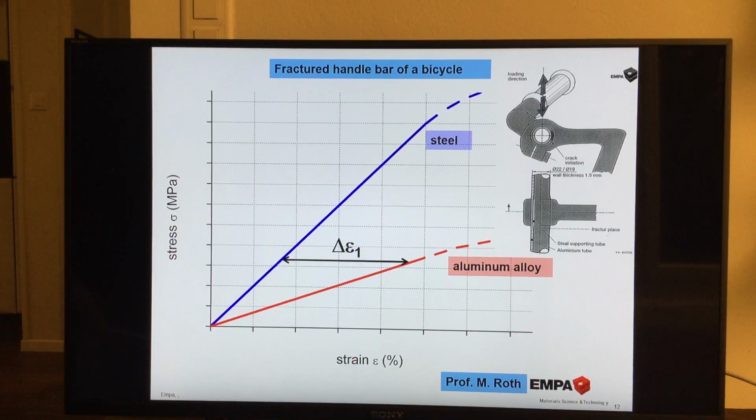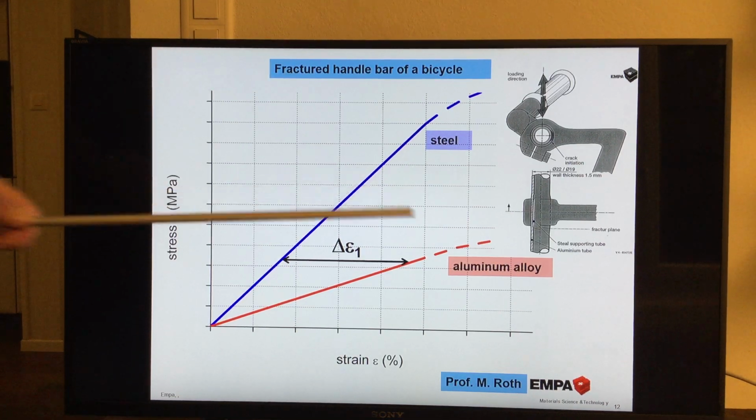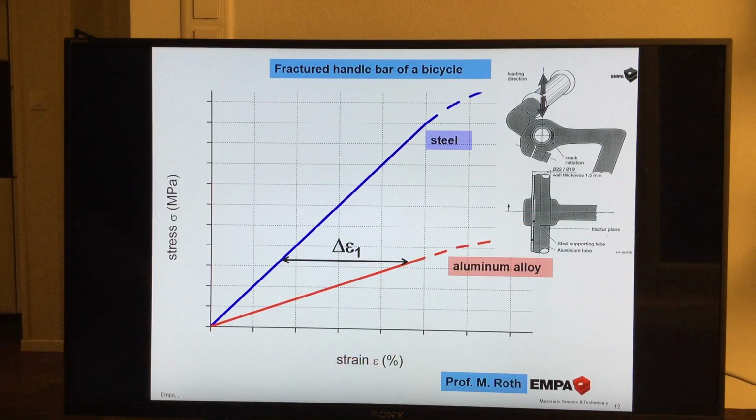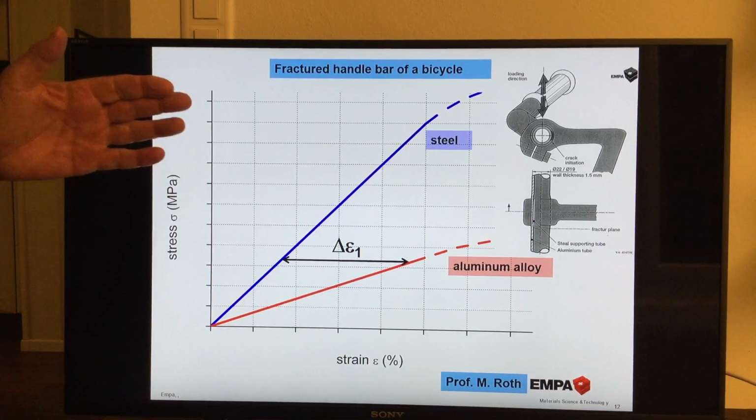Strain is deformation. And this difference in deformation we clearly have seen in this movement of the materials scratching the aluminum alloy and destroying the aluminum oxide layer. That's very important. That's a main mechanism. The other mechanism, that there is maybe also some corrosion, we have additionally seen, but that's a main point.